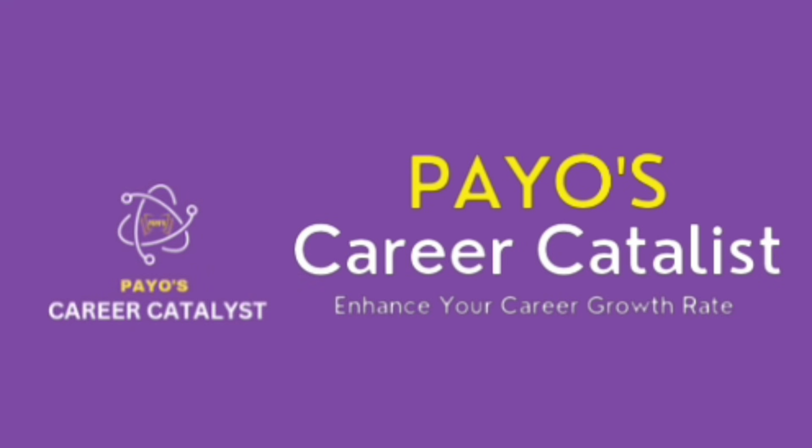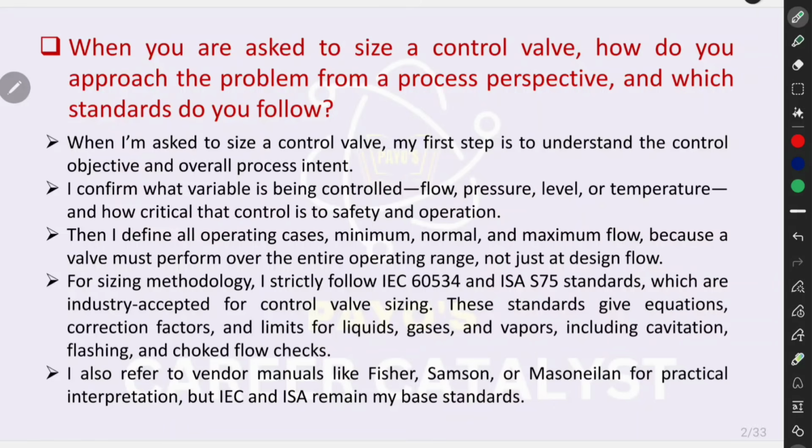When you are asked to size a control valve, how do you approach the problem from a process perspective? And which standards do you follow? When I'm asked to size a control valve, my first step is to understand the control objective and overall process intent. I confirm what variable is being controlled: flow, pressure, level, or temperature, and how critical that control is to safety and operation. Then I define all operating cases: minimum, normal, and maximum flow, because a valve must perform over the entire operating range, not at just design flow.